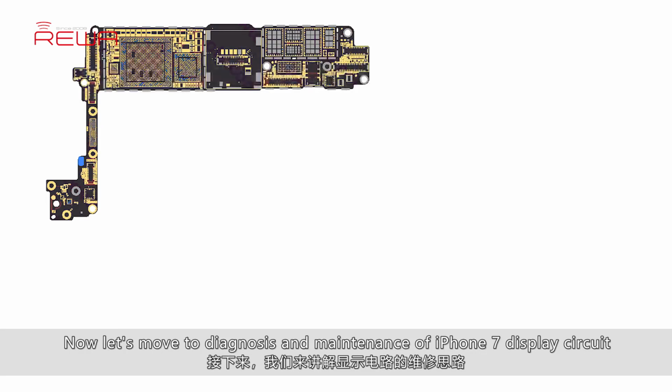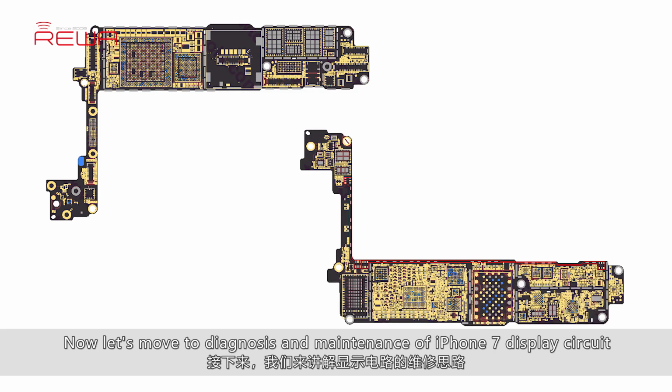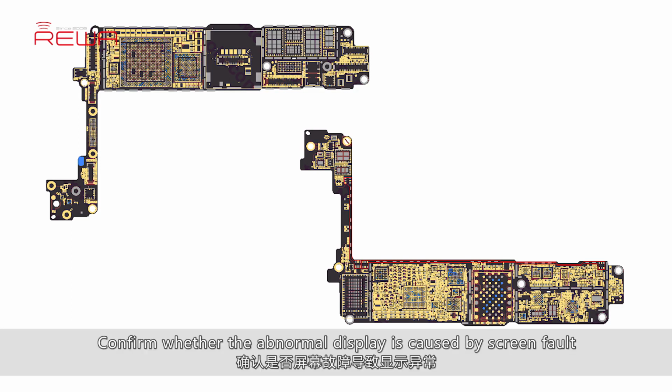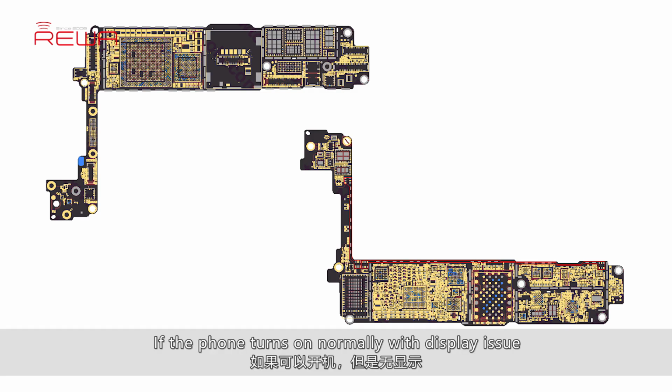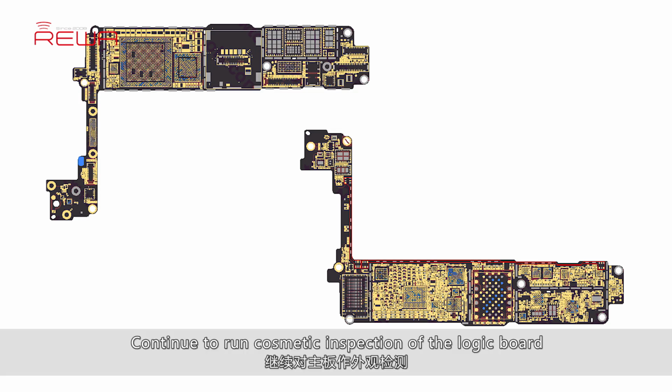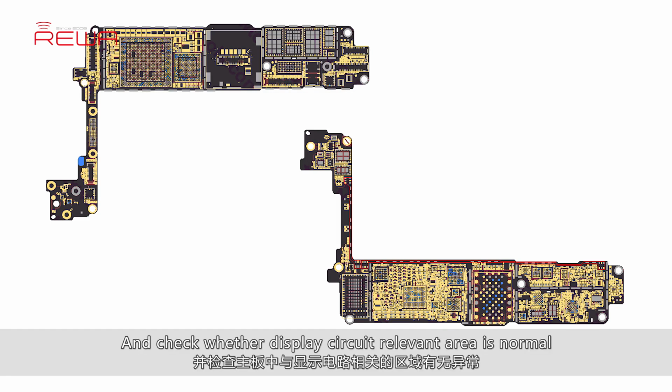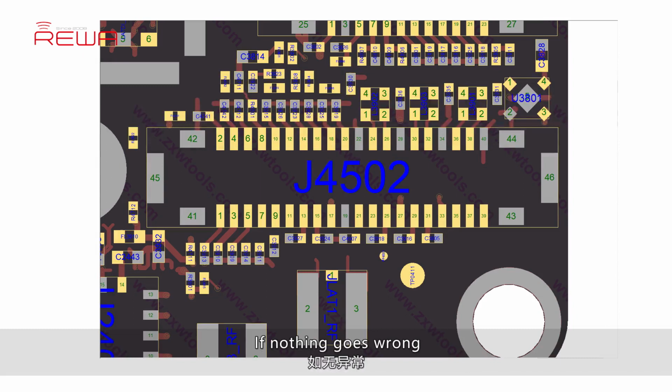Now let's move to diagnosis and maintenance of iPhone 7 display circuit. First, replace the screen, power on and test. Confirm whether the abnormal display is caused by screen fault. If the phone turns on normally with display issue, then the fault is related to the display circuit. Continue to run cosmetic inspection of the logic board, and check whether display circuit relevant area is normal. If nothing goes wrong, we can start the maintenance work from two aspects.